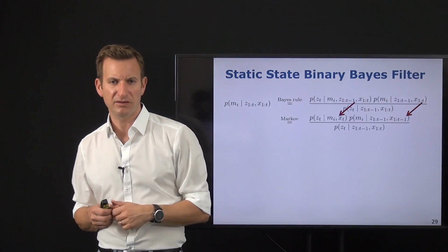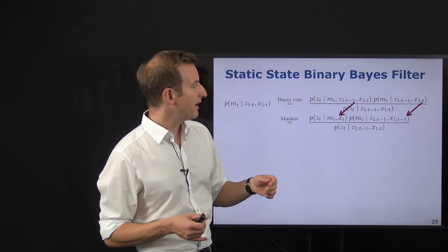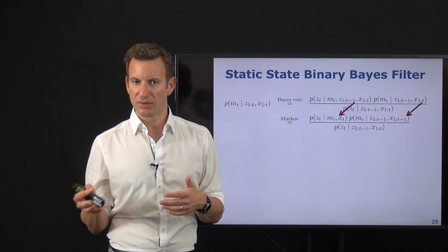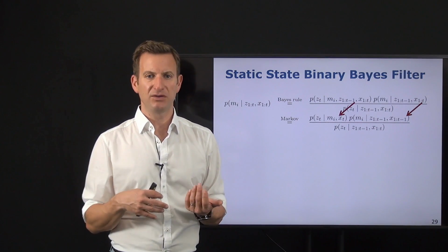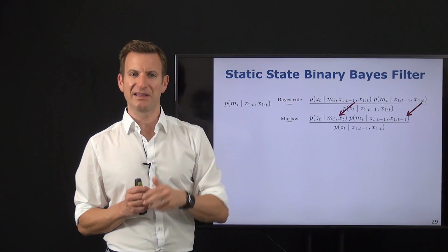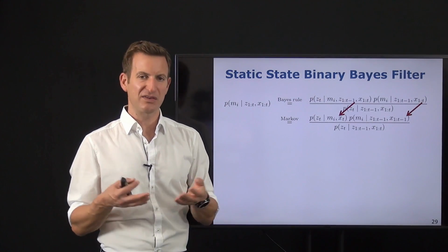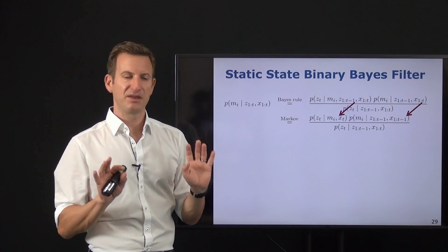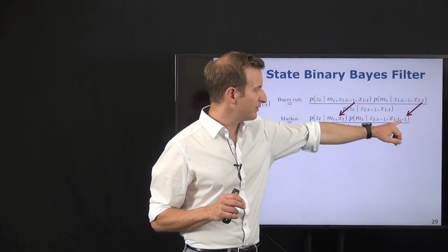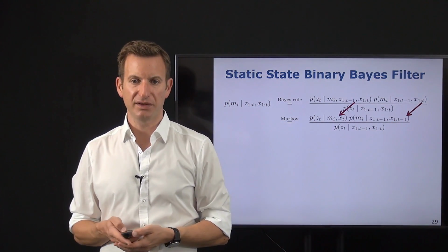This is similar to the independence assumption that we also used in the derivation of the Bayes filter, by saying that wherever I am in the future, without any sensor information, doesn't help me to estimate if a cell is occupied or free. The only exception might be if I'm actually standing in that cell. Then I could say, okay, this should be free because I'm standing here with my camera or with my laser range scanner or with my robot. But again, this is an independence assumption that we are dropping here. So we drop this future position and just ignore xt over here.